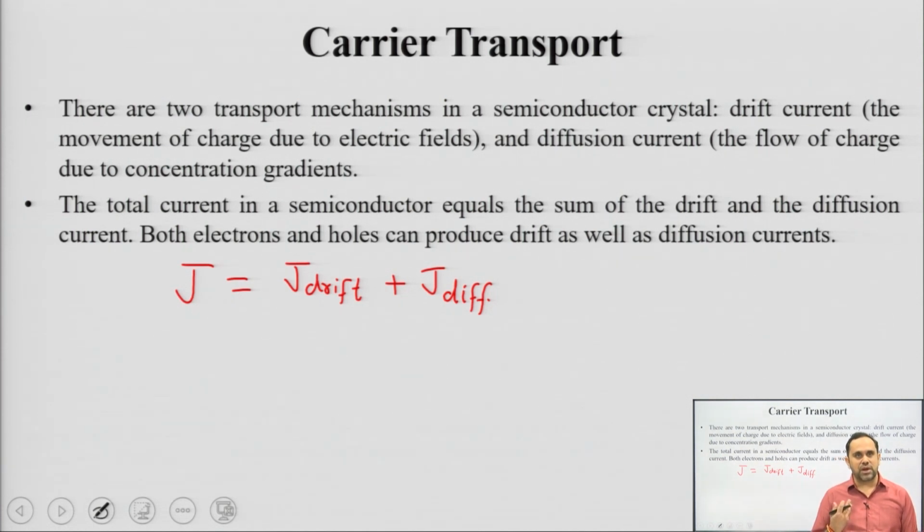So, diffusion in general is a process where a particle or molecules or something flows from a higher region to a lower region, and when we are talking about these doped semiconductors, we are talking about the gradient of the concentration. Okay. So, if you have higher electron concentration spatially with respect to distance between 2 points, you can have diffusion current with charges flowing from higher concentration to lower concentration. Okay. So, diffusion is always going to occur from a region of higher to a lower concentration, and it is going to happen for both electrons as well as holes.